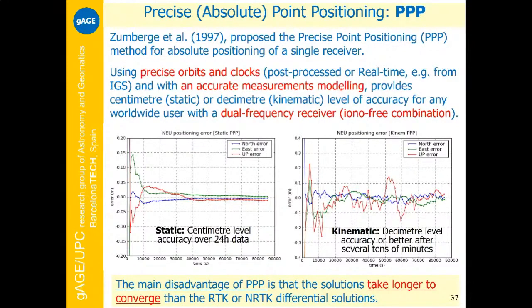In the case of RTK, in the previous case, there is no problem with solid tides because the reference station and user are close and in a local area, and then they move due to the solid tides in the same way and cancel in differential mode.